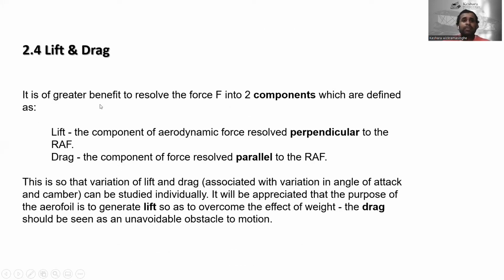It is of greater benefit to resolve the force F into two components, which are defined as lift, the component of aerodynamic force resolved perpendicular to the relative airflow, and drag, the component of force resolved parallel to the relative airflow. Right? This is so that the variation of lift and drag associated with variation in angle of attack and camber can be studied individually. It will be appreciated that the purpose of the aerofoil is to generate lift so as to overcome the effects of weight. The drag should be seen as an unavoidable obstacle to motion.